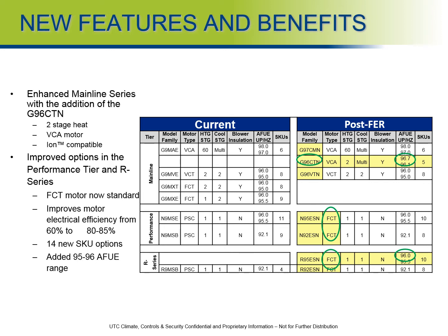This in turn references the static pressure that the system is working against. As it communicates those RPMs back, the control board converts that into the pressure that the blower is working against, and therefore can ramp the motor up and down based on that pressure variance.